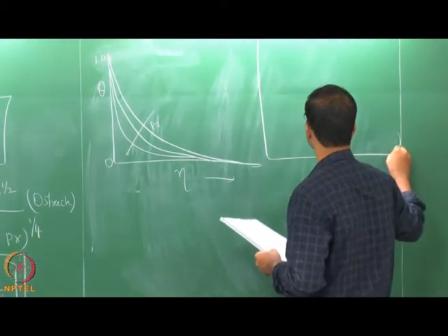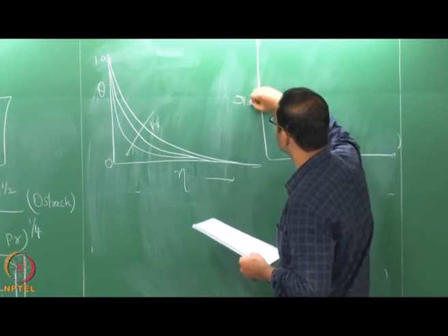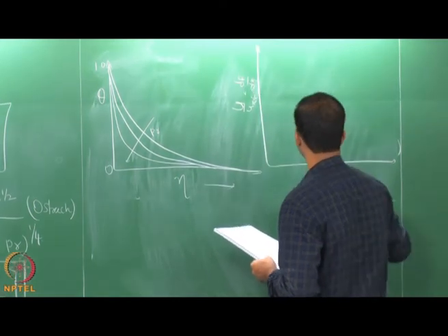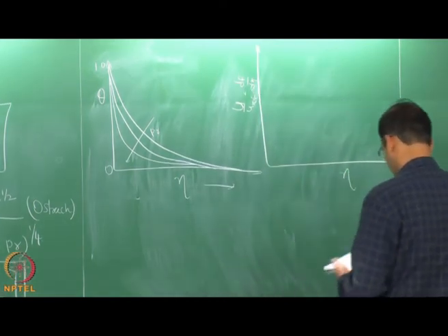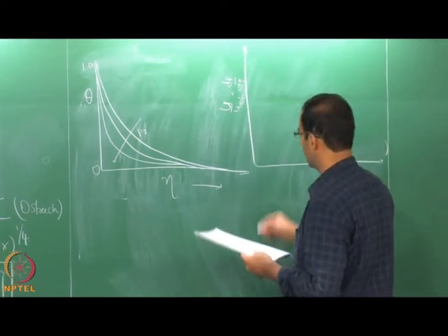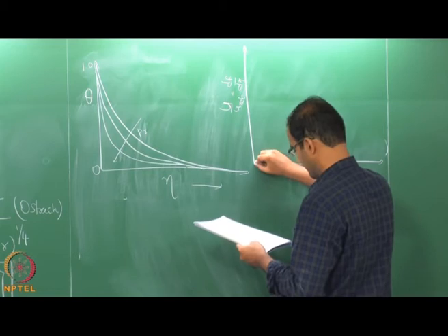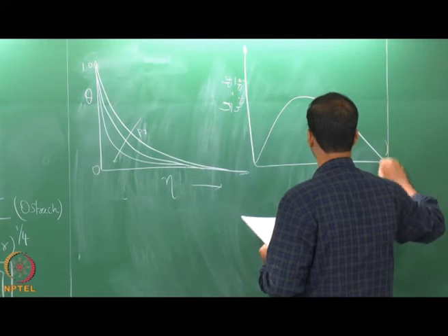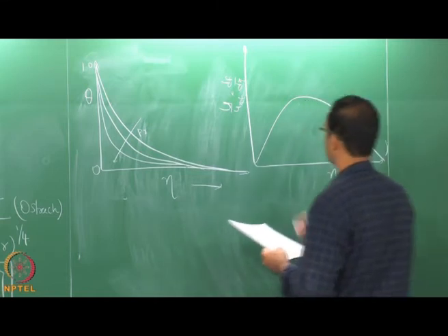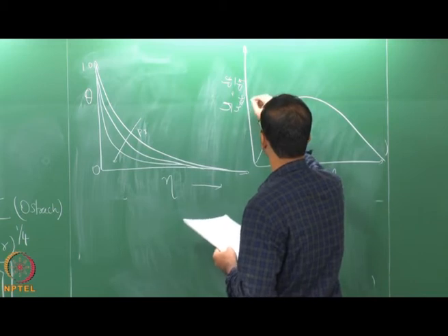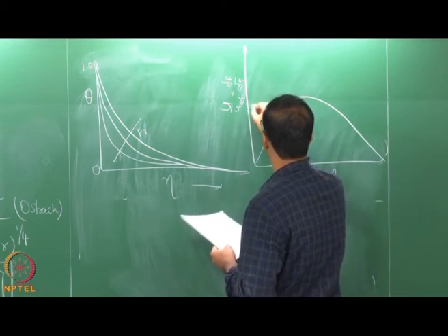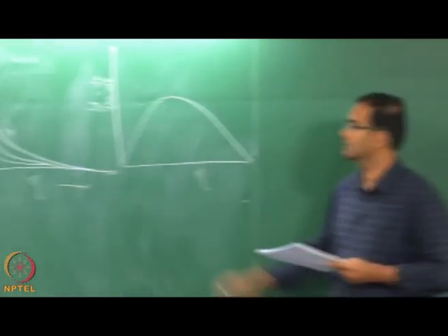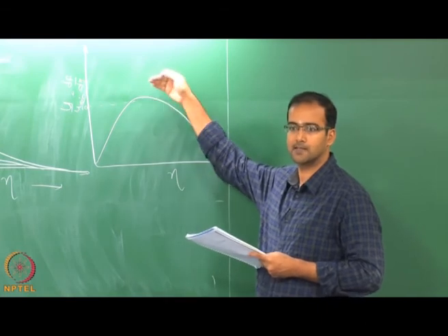Similarly, if you plot your u by u ref, which is nothing but df by d eta as a function of eta. Okay. So, this also shows a functionality with Prandtl number. So, you find that something like this. So, it reaches a value of 1 depending on what you take as your u ref. Okay. So, suppose somewhere here it is your u ref, it reaches 1 here, okay. And if the peak is not your u ref, that will exceed 1.